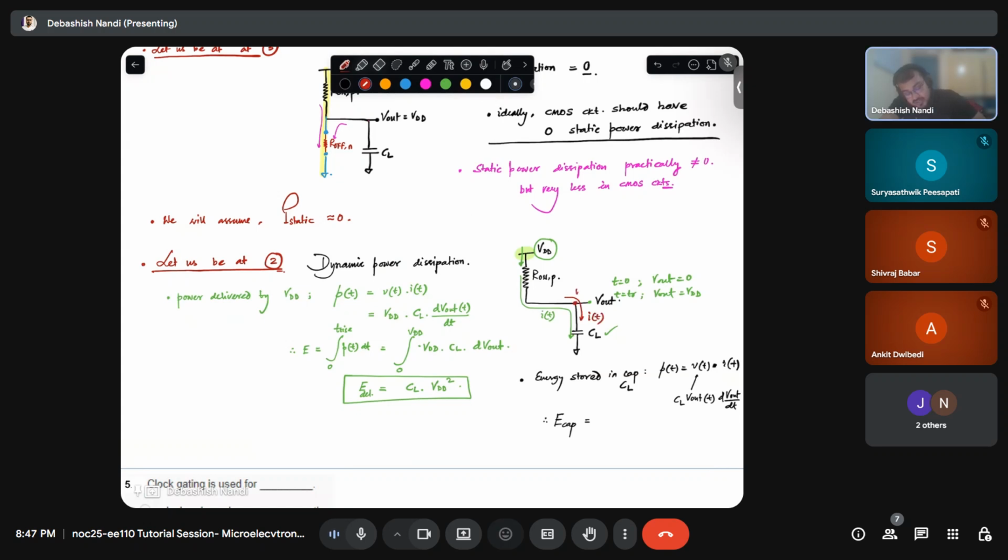What is the voltage? V(t), V out of t. So what is your current? C dV by dt, right? CL times dV by dt, where V is the voltage across the capacitance. Yes, sir. I have written that, right? Okay, sir, a little bit of confusion, okay, not an issue. So if you calculate the capacitance energy stored, it will come out to be half CL VDD square.